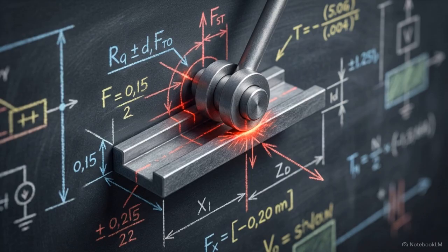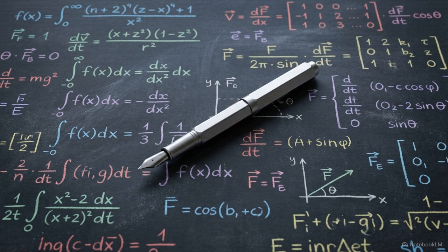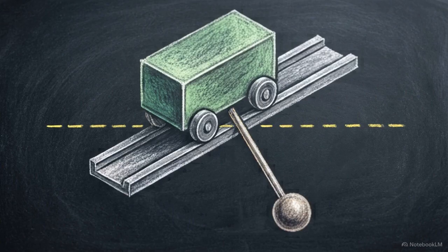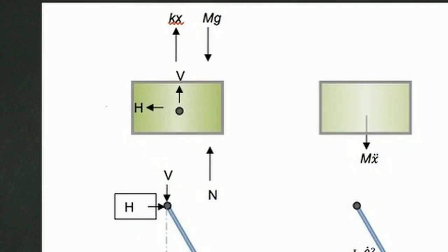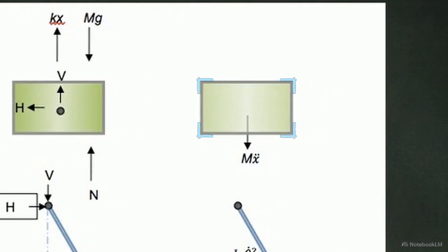Because the pendulum's rotational swing exerts reaction forces that impact the horizontal slide of the cart, their physical motions are mathematically coupled. Untangling them requires a systematic Newtonian derivation. The first step of this derivation requires us to isolate each body visually. This allows us to analyze the forces acting on each mass independently. This diagram isolates the green cart block. On the left is the free body diagram, showing physical forces, and on the right, the kinetic diagram, showing inertial forces.